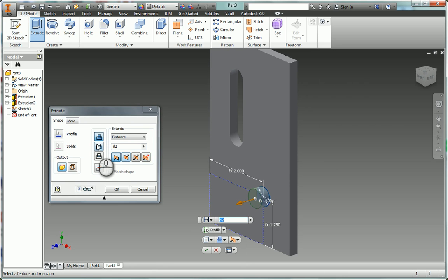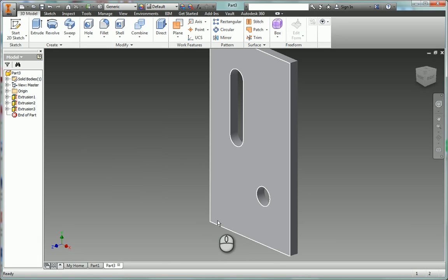We're going to cut it instead. And how far are we going to cut it? See, the whole extruded length is called D13. D13 equals, and it's going to be the same as the slot height, which was D8. That would have been D8, which was the same as D2. So we'll just do equals D8. Return. And then, of course, that probably added a D14 on there.